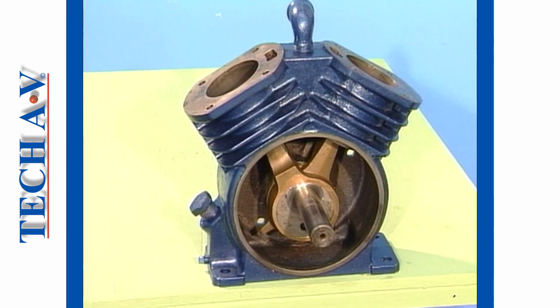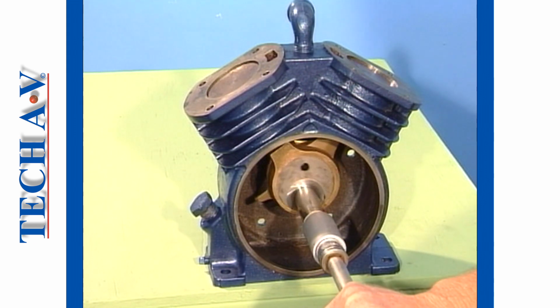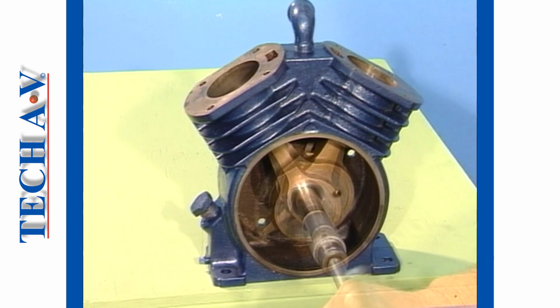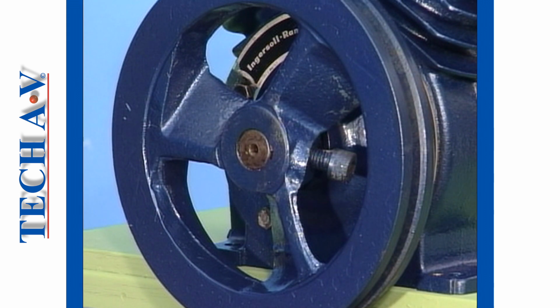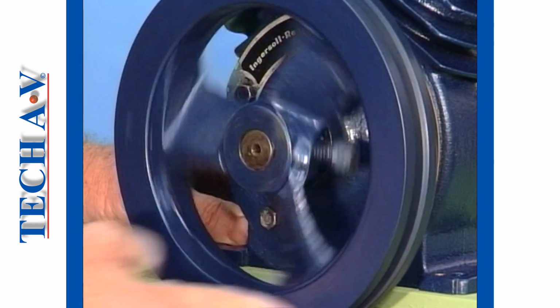The pistons fit into their respective cylinders, and as the crankshaft is turned, the connecting rods force the pistons to move up and down within their cylinders. The crankshaft is supported at either end, in this example, on bush-type bearings. A flywheel is attached to the end of the crankshaft. The flywheel also acts as a belt drive pulley and a cooling fan.